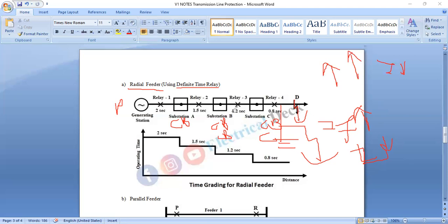So this system is not suitable for ring main systems or interconnected lines. It is only suitable for a radial line supplied at one end only. It is also not suitable where coordination needs changes with new connections, nor for long lengths of line. Continuity of supply cannot be maintained at the receiving end of the fault.